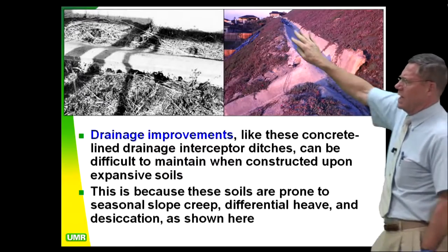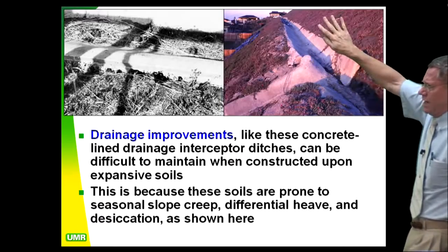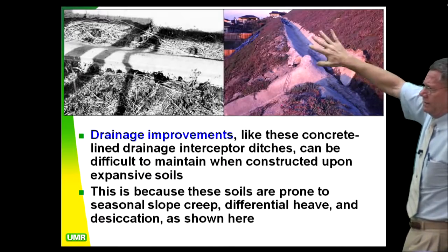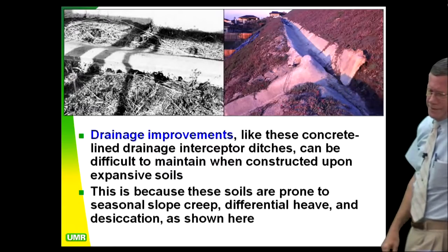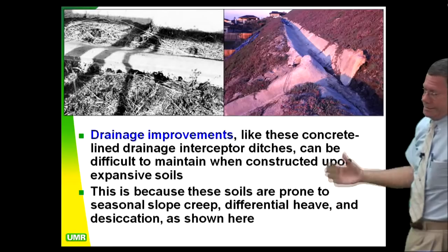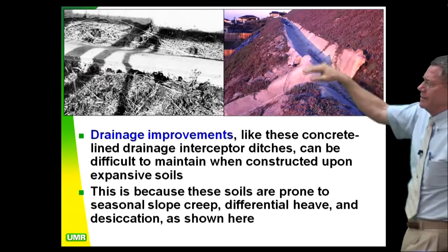And if you put in your concrete drainage work and flat work in the dry season and you let this get too dry, now when it gets wet, you're going to get noticeable heave, and it's just going to break your concrete flat work. So it's not fun to go out there and put it in, but the wetter the slope is when you put it in, the better.